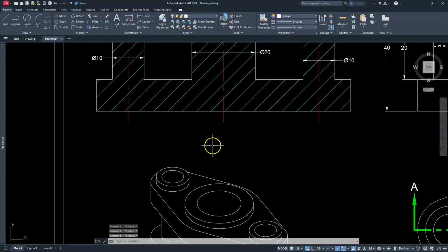All right, kind of coming up below this, I'm going to use that same method here. I'll go back to standard text, right? And this time I'll use that text and I'll make it 7.5. So it's going to do the math for me. I'm going to justify this one by the MC, which stands for middle center. I'll click somewhere in the middle of this point. So I'm just tracking off of it to make it here. Text height here, let's make it 7.5. Hit enter. And then hit enter one more time because we have a 0 rotation angle. Now it's ready for me to type.